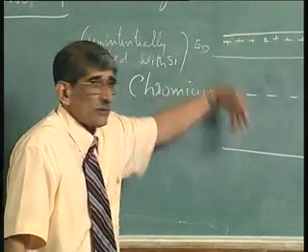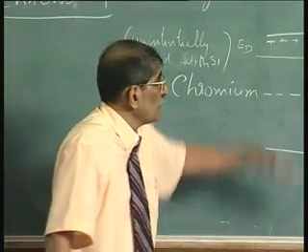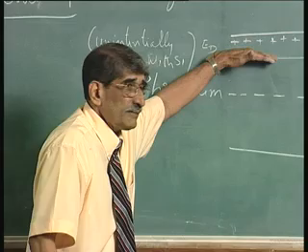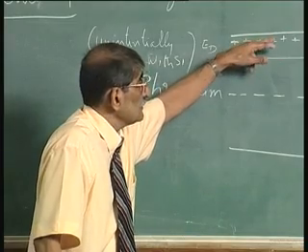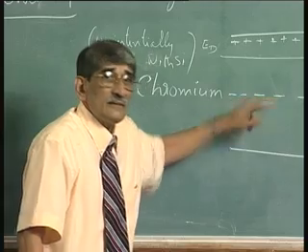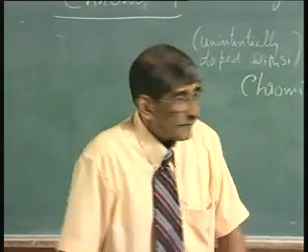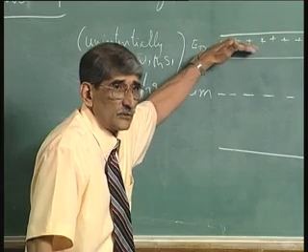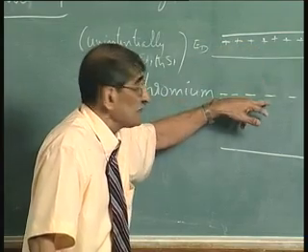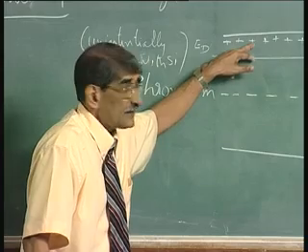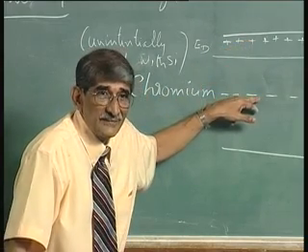It can go up or go down, whatever. So, if you add here, the Fermi level is here initially, this is not occupied, that is donated electrons, this is occupied. So, if there are 10 to the power of 15 electrons here due to donors, when this is 10 to the power of 12, after those 10 to the power of 15, 10 to the power of 12 will go down here to occupy that.